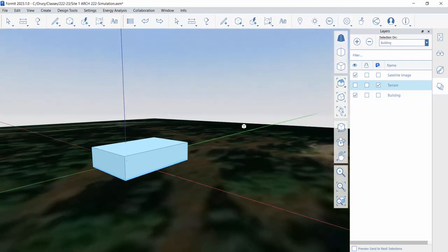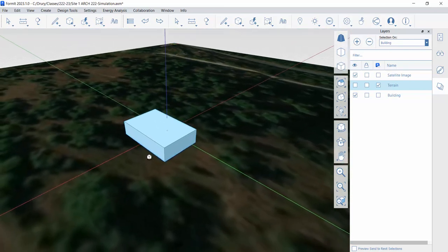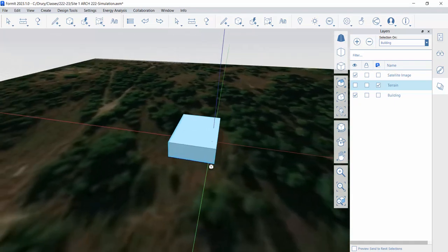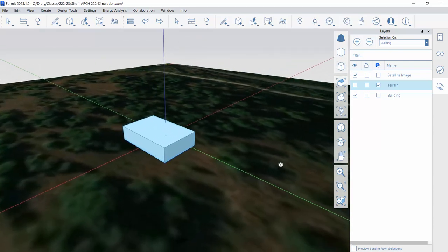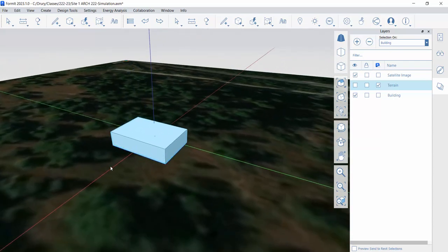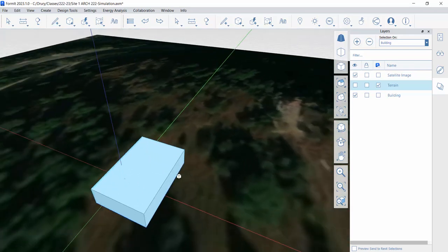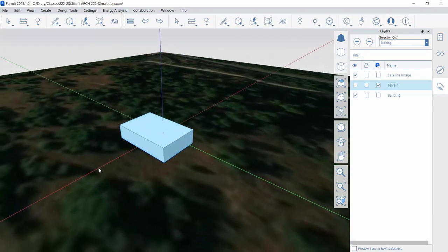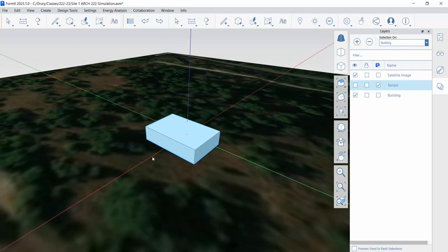And it knows we're right now doing this just off of a massing form, right? Just a very, very simple massing form. Again, we're thinking about pre-design simulation. I don't have any windows decided yet. I don't have my roof form decided yet. None of those things are in place. But the Insight tool set that we're going to next will actually create a lot of design variables for us that I can then push back into FormIt in terms of making informed design decisions about number of windows, orientation of the building, all of those things.